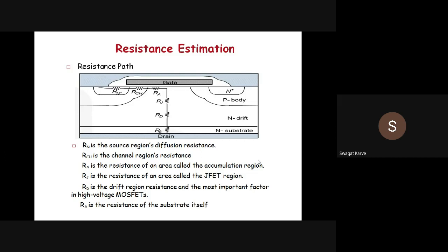Whenever the MOSFET is in the linear region of operation or resistive region of operation, in that region the MOSFET will behave as a resistor, as the characteristic you are getting is very linear, that means current and voltage have a linear proportion. That's why it must exhibit some internal resistance in series by its geometrical structure.